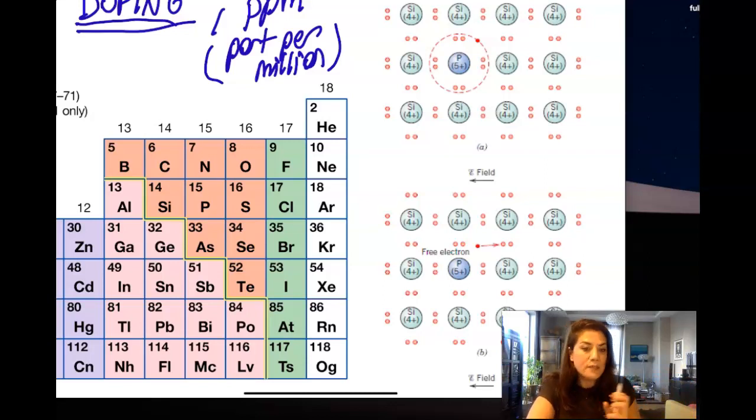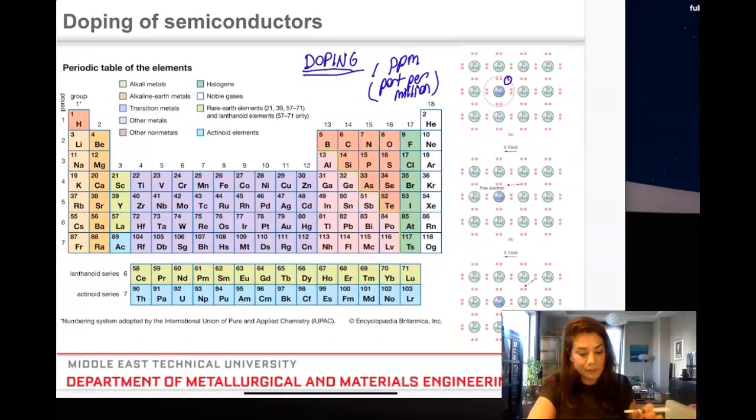But you substitute, they don't go into interstitial sites, right? They substitute the silicon atom. To have interstitial positioning, you need a significant difference between the atomic radii. So you substitute the silicon atom with phosphorus. Look what happens. Since phosphorus atoms have one extra electron in the valence shell, it forms the covalent bonds with the silicon, substituting that silicon atom, but there's one extra electron here that can be utilized as a free electron in the conduction band, right?